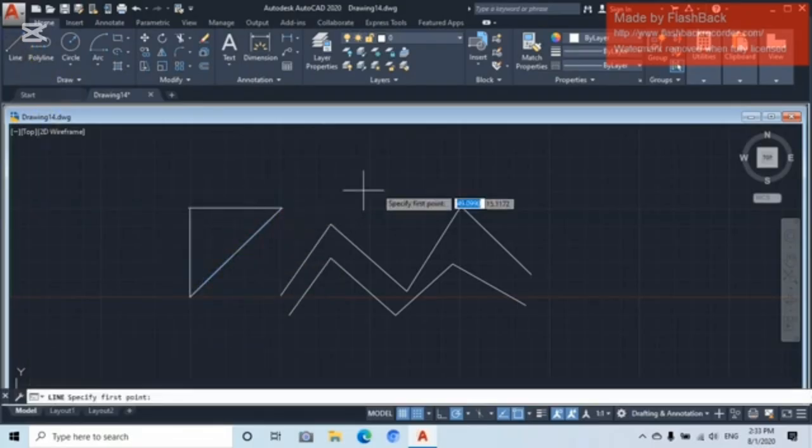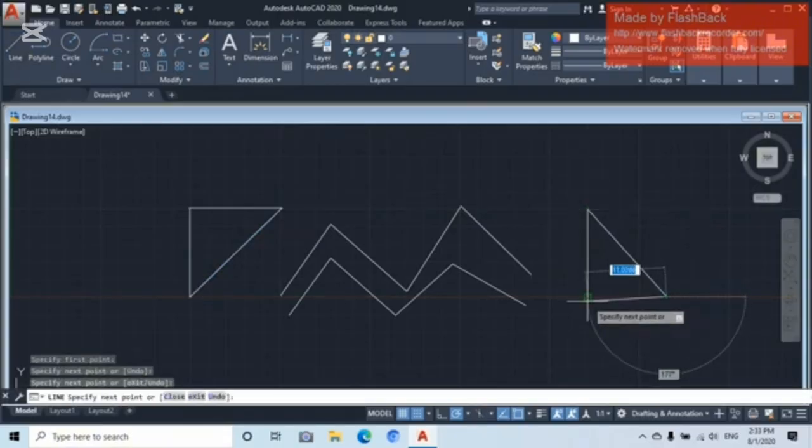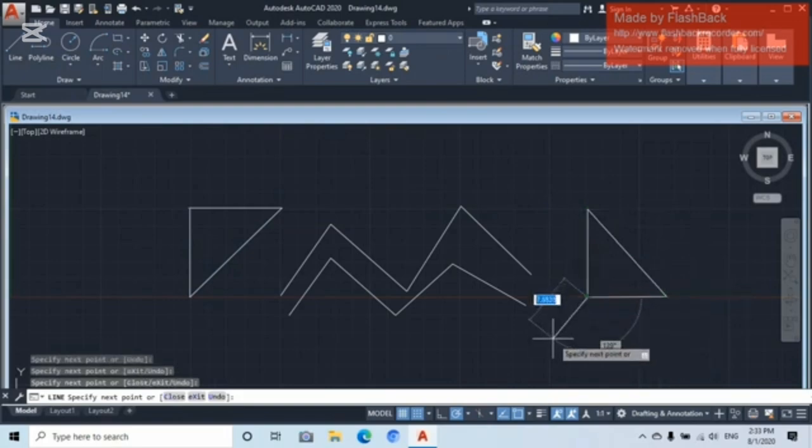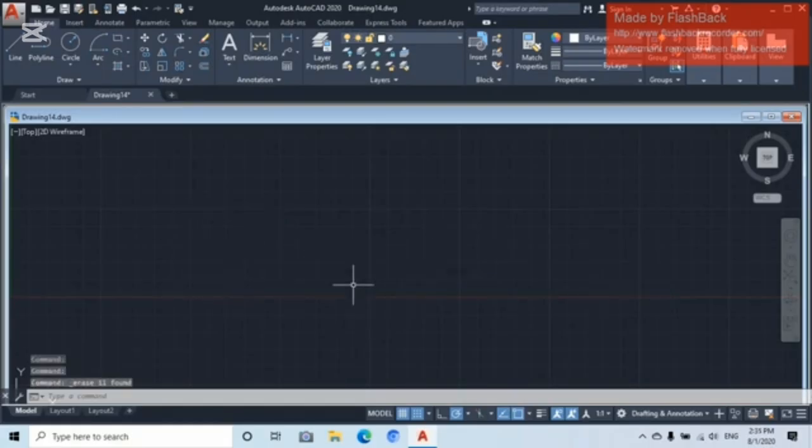What if we make a triangle with a line? Okay, let's use a line to make a triangle. Escape. Then when you select on a point, just the length of the line segment will be selected. Okay, then with polyline, everything is going to be selected. So that is the difference between line and the polyline. From here, we're going to move straight to do our first drawing.